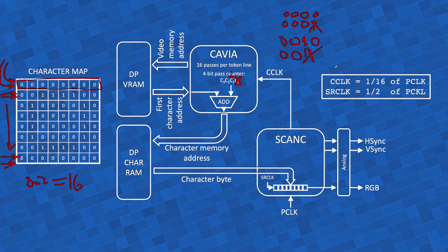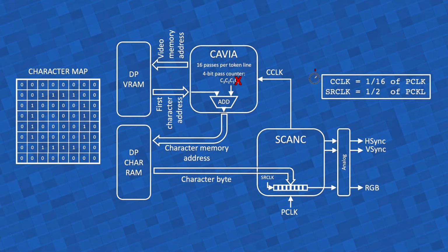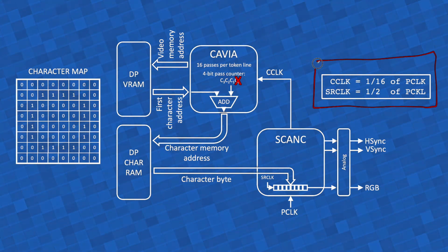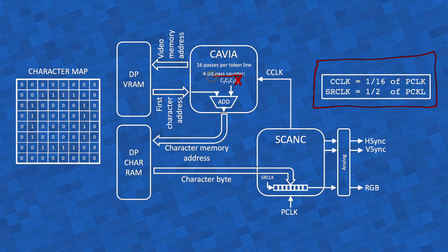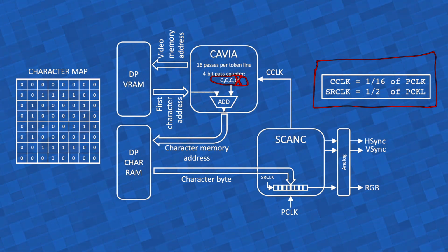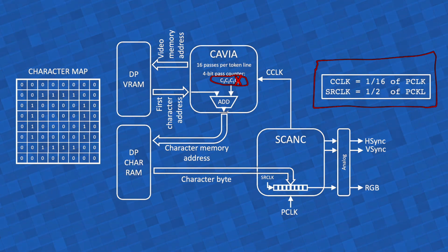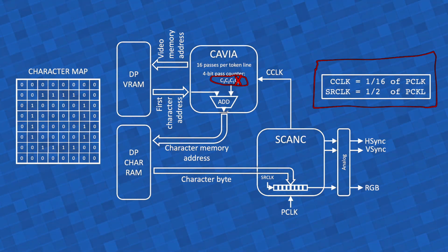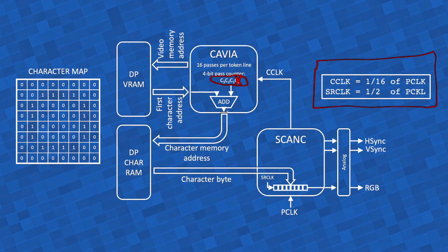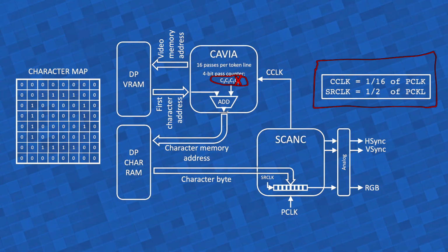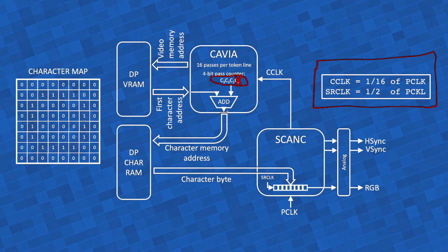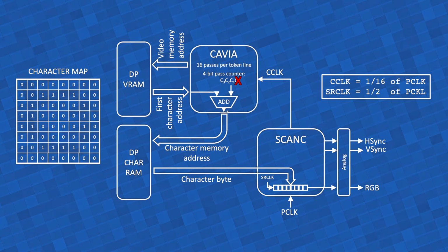So by doing these 2 simple things here, and this small trick here of using a 4-bit counter but ignoring the least significant bit when you index the specific byte, we double the size of the screen and we can fit everything neatly and nicely into the VGA mode I've chosen. That's about it.